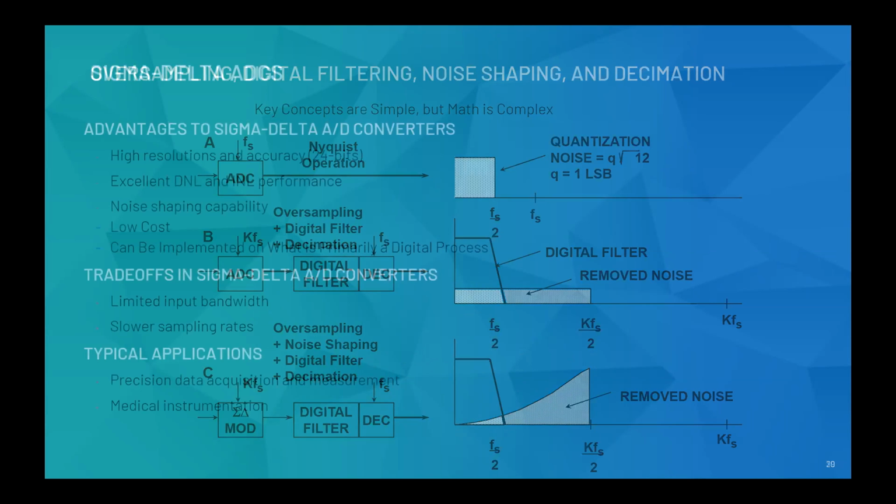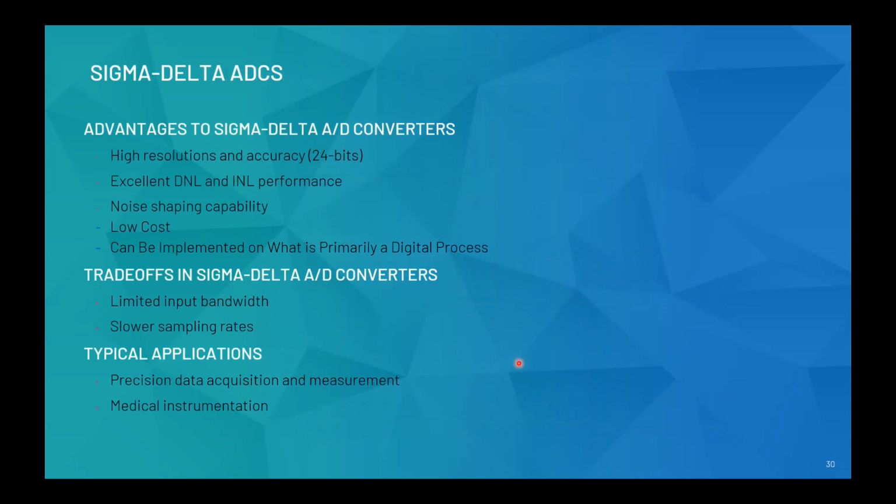All right. So sigma delta ADCs have some advantages. High resolution, unlike the SAR. We don't go through comparisons every time. We generate a bit stream at a very high frequency, and then with an averaging filter or digital filter, we go on accumulating them. This helps us achieve high resolution and high accuracy from the bit stream.